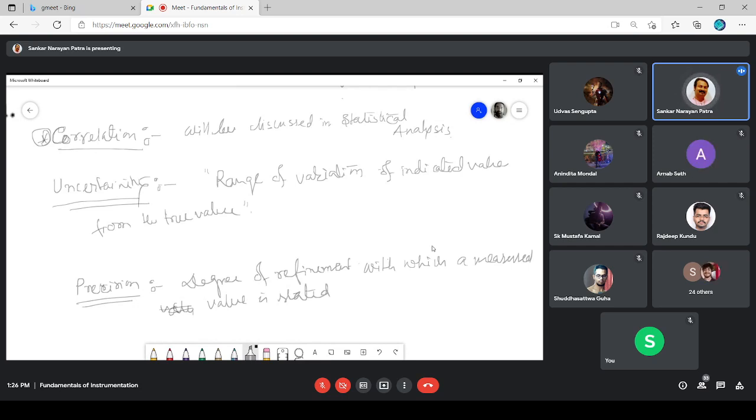Next day it shows 95.6. Next day it shows 90.1. Then if you find the characteristic of the instrument, you will see that it never reached 100, so it is not at all accurate. Rather, it sometimes shows 90 degrees centigrade, which is much less accurate.